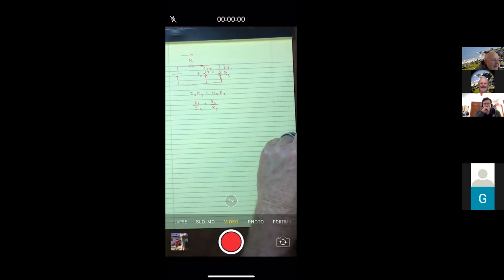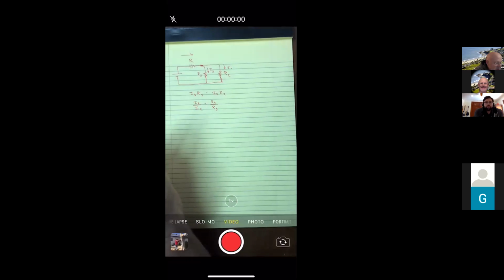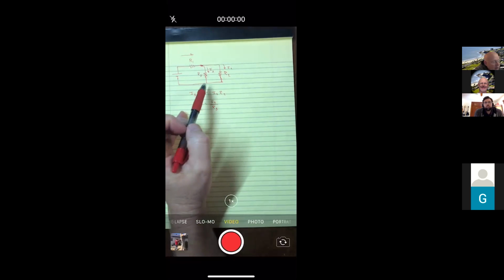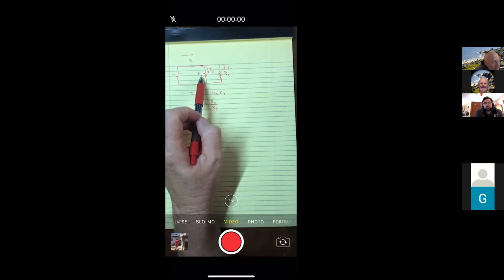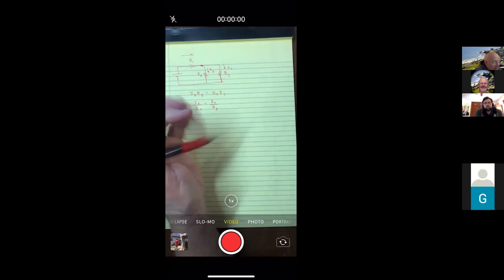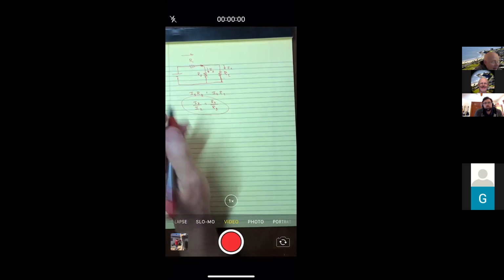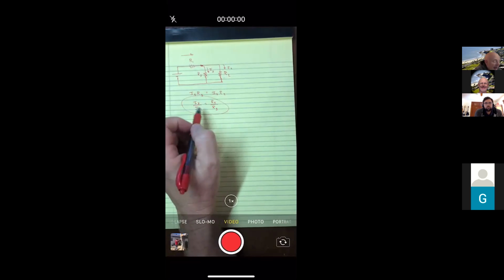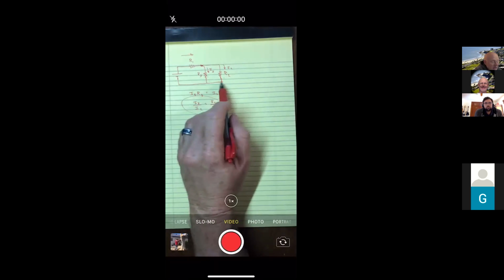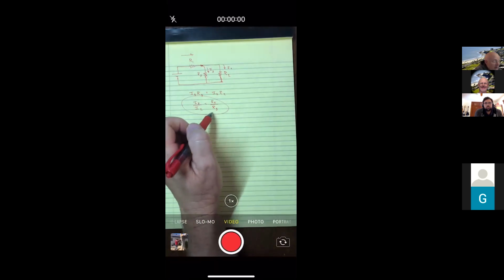situational. Yeah, I don't really like it, because when you say electricity will go the path of least resistance, it almost sounds like you're saying, well, if resistor number 3 is less than number 2, then it will all go through number 3. And that's not what will happen. It will split. We call these current dividers. And how much it divides depends upon the resistance ratio.